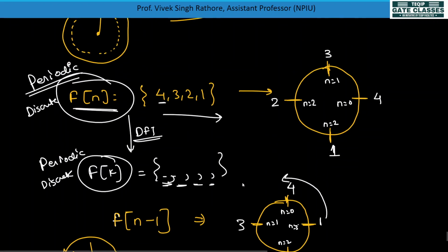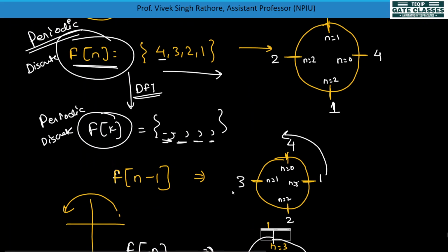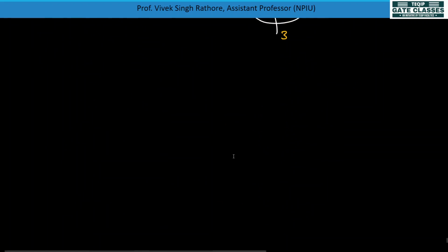Now you can see what I have told you ultimately from this expression is circular. Why are we doing circular convolution? Because in a DFT type of transformation, the signals are discrete and periodic, first of all. For this type of periodic and discrete signal, we can put it in a circle and solve. In linear form you can also solve, but the value comes in the shortest form this way. So we'll try one or two questions, then only will you be able to understand the concept.